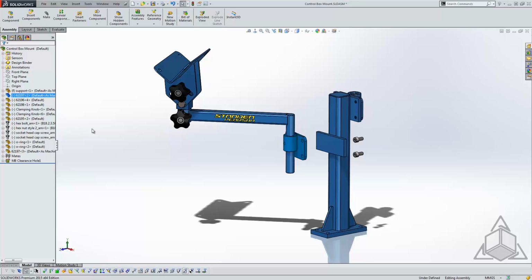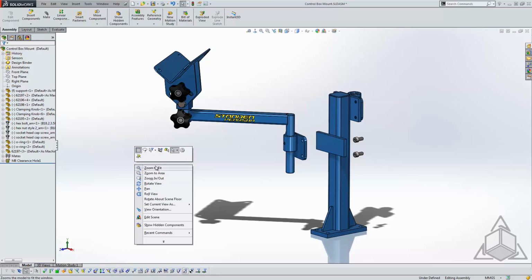Like I said, that goes across the board, whether parts or whatever you're working on, but it picks up the last piece. This can be very helpful if you've got something selected, or many things selected, and you go to click on something else and you miss the control key, and it deselects all of those things you've picked up. I know that happens to me fairly frequently, right? You bump your finger off the control key or don't press down hard enough. Previous selection will pick those things back up for you, and I've had that come in handy several times since loading 2015.